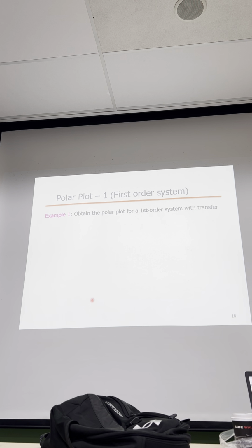And let's put it this way. Based on this transfer function, I'll get the amplitude ratio, based on the formula where T is the time constant and K is the gain constant. So K equals 3 and T equals 2. So you get the formula with only the term of omega.